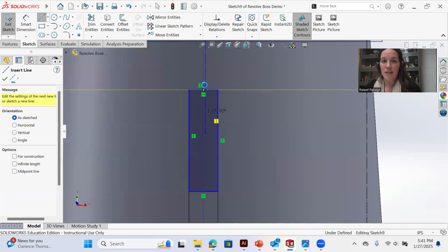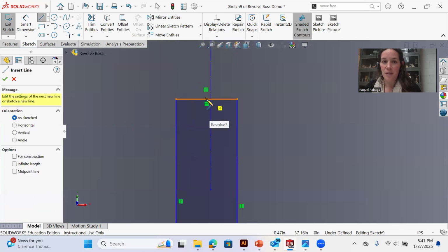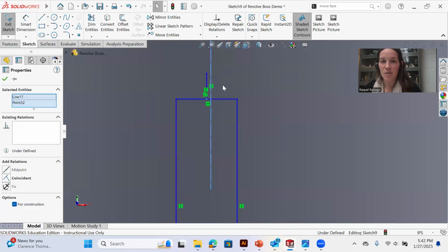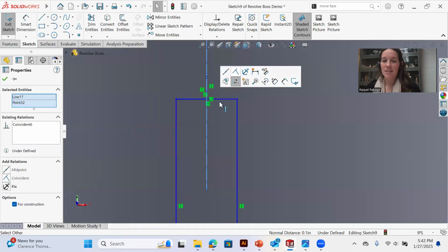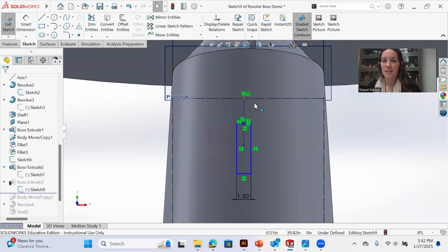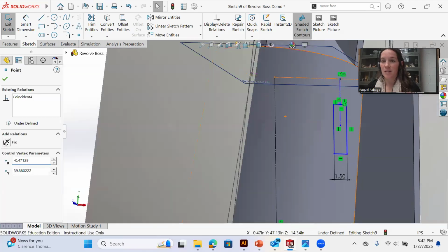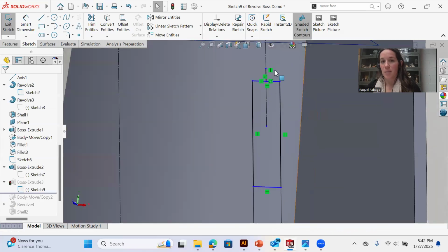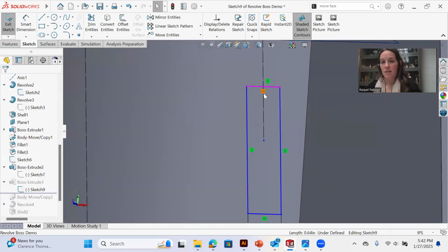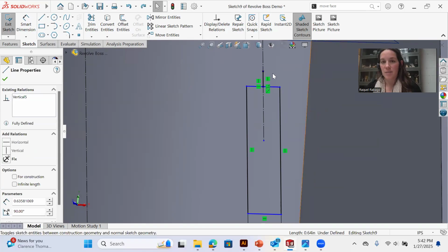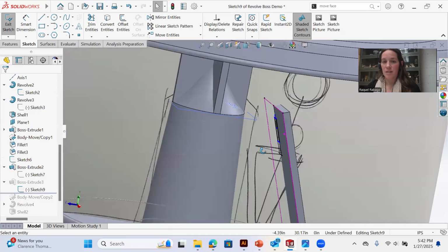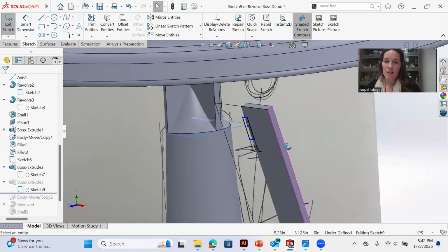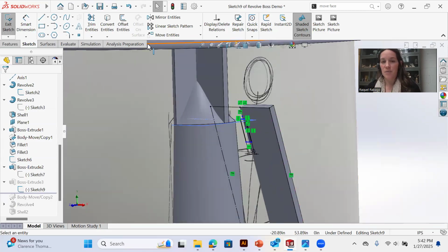So you can choose. There's an easier way to select that midpoint, but I'm not gonna go through that right now. Make coincident. And then make that the midpoint. Those of you who have Rhino experience are probably well aware of all the ways that this works in Rhino. It's pretty similar in SolidWorks as far as assigning constraints to things. So